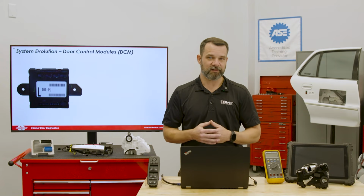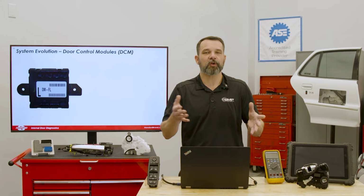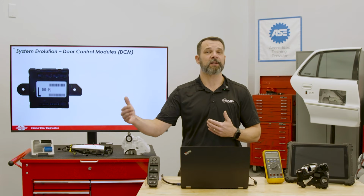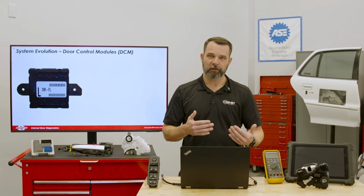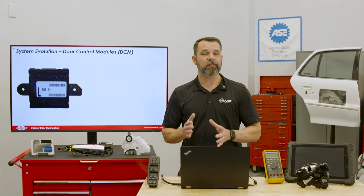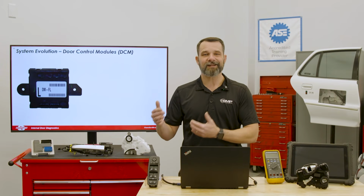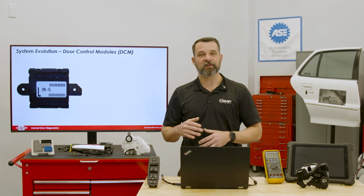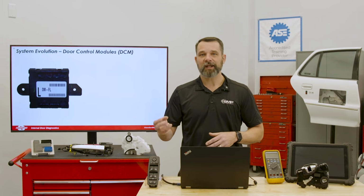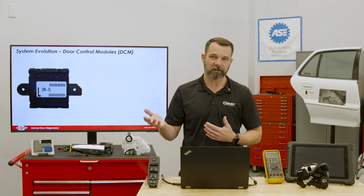So what is this DCM? It's the same thing as a BCM in a way. It's a small module or a control unit located inside the door itself, and it functions as that local brain for the door. So instead of the BCM directly powering or monitoring every switch and motor, like our previous example, the DCM handles all the real-time door functions. Now, this design reduces a lot of wiring and complexity, and it improves response time as well, especially for features like one-touch windows, mirror controls, and the lock logic.